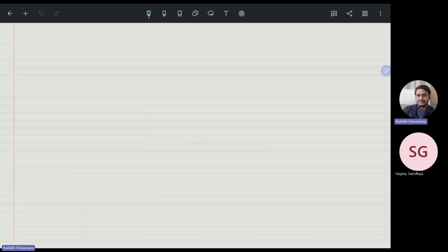Now we have another question. You have a pipe and there is a sudden enlargement happening here from 100 to 200. If at this location the velocity is 8 meter per second, we need to find the pressure drop at this location because of the sudden enlargement.